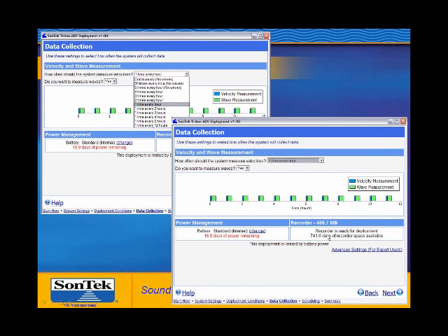And that's when you have to do what we like to call the compass dance, where you have to rotate the entire system around at least a couple times while varying the pitch and roll as much as possible. What that will do is that the compass will be sampled this whole time, and will say, okay, I am becoming aware of what the magnetic interferences around me are, so I will compensate for them. One other thing I'd like to add on the calibration is that the ADV itself does not require any calibration, and that compass calibration is typically to compensate for any site variations in the magnetic field. Correct.